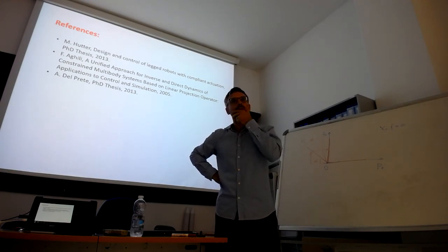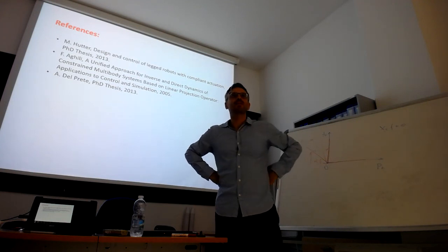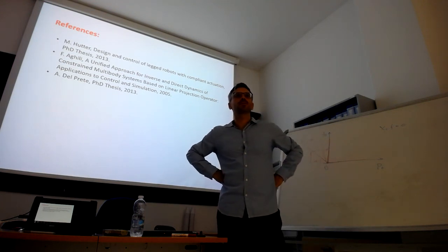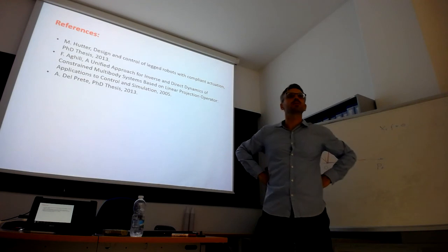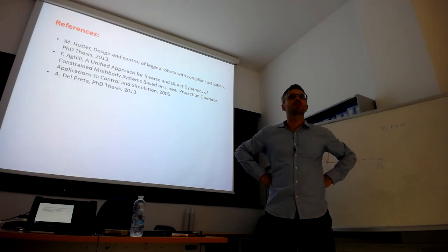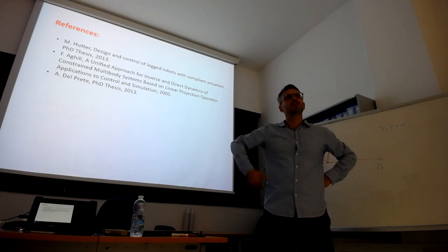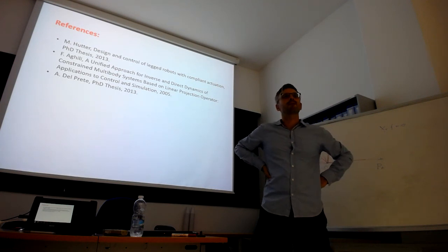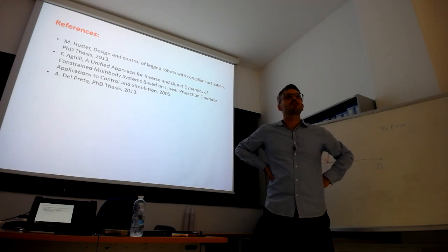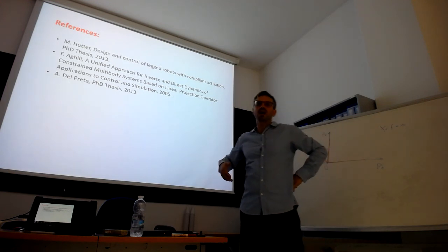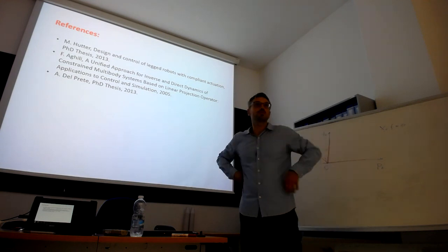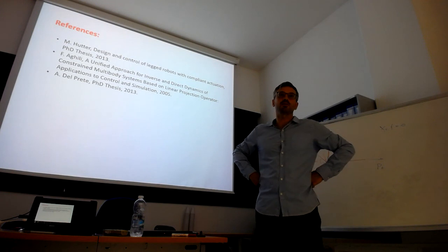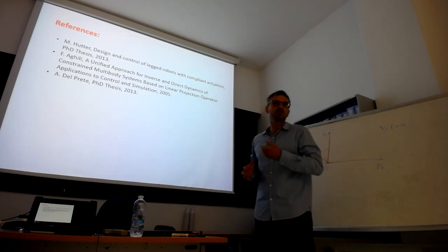Yeah, because that would actually solve a problem of having the pseudo-inverse in the formulation. Let's say if we were to consider the optimization and directly take the least square formulation in the optimization, with bi-level optimization, you could actually have two objective functions interacting with each other, where one is doing something at the planner level and another one where you have to find the solution for this QP, so finding the inverse of the pseudo matrix using only optimization rather than doing the pseudo-inverse separately. Yeah, this is just an alternative, but nobody does it, I think because it's time consuming. Just computing the constrained inverse dynamics was just to show that it's equivalent. It's not of practical use, I would say.